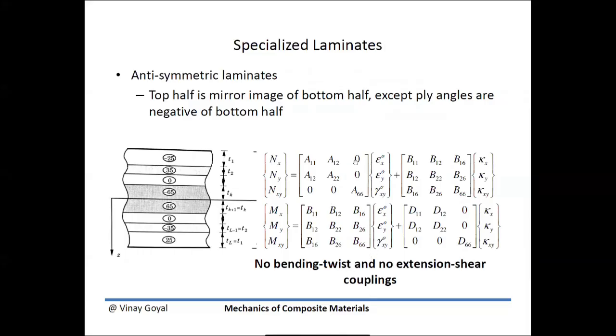So you don't have these components right here in the A and D matrices. And feel free to pause the video to study what is going on. I think you will see here that these two right here are not contributing to the calculations of the force resultants, and these two are not contributing to the calculation of the moment resultant.